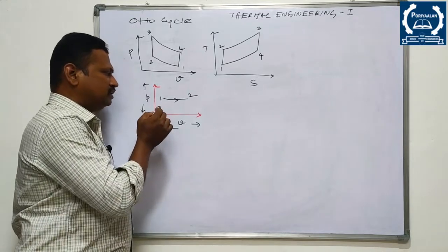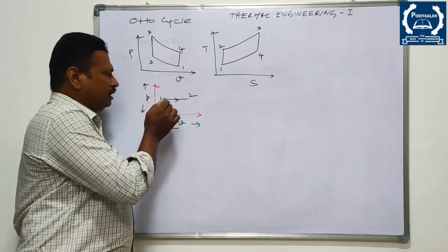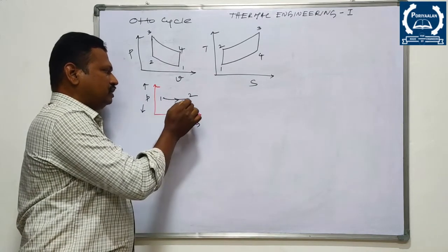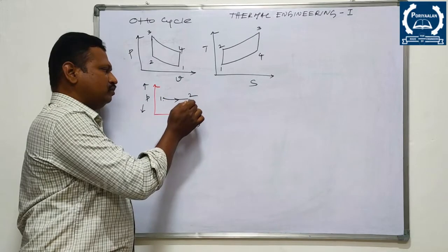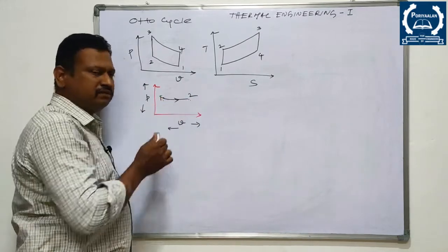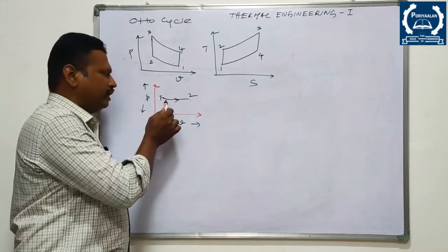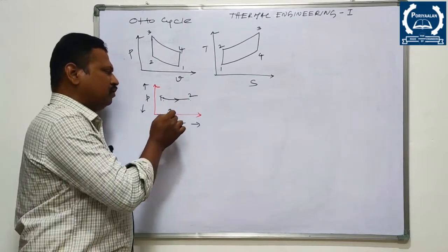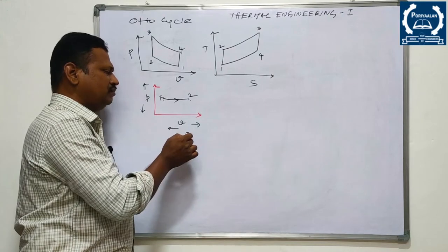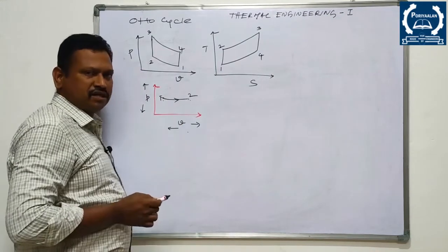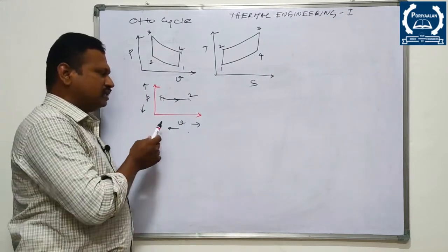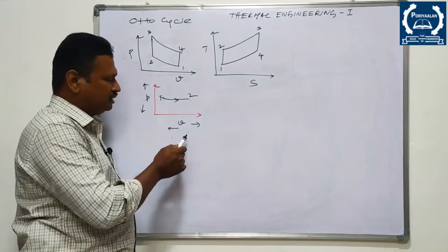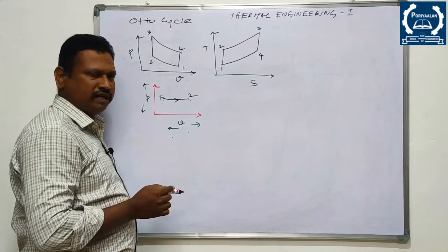So, as far as this diagram is concerned, there won't be any change in pressure because these are two states. State number 1, state number 2. You may know that state is nothing but a characteristic of a system at a particular point. So 1 to 2, a change of state, is known as a process. So when I am going towards this direction, volume increases. So pressure remains constant. So this is nothing but a constant pressure expansion process because volume increases, pressure remains constant, right?